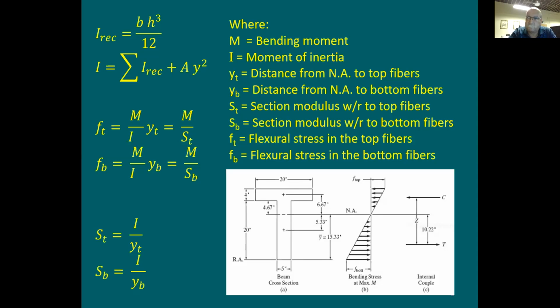When the beam section is reaching or approaching this moment value, this beam is going to start to crack. Very similar to the term cracking stress. What's the cracking stress? The stress at which the beam at the bottom tension is going to start to crack. Just a value, a limit. So let's say 400 psi, which means when the stress here becomes 400 psi and above, the beam is going to start to crack. How about cracking moment? I can throw out a number just for the sake of discussion. Let's say 20 kip-foot. When this beam reaches 20 kip-foot as a moment value, this beam is going to start to crack.